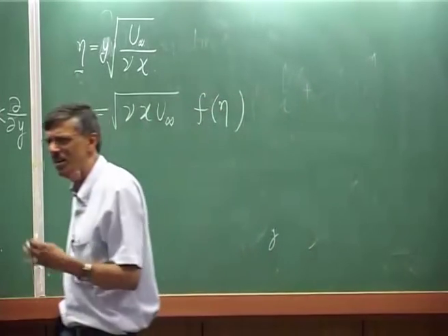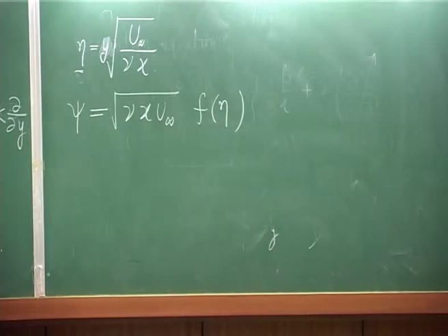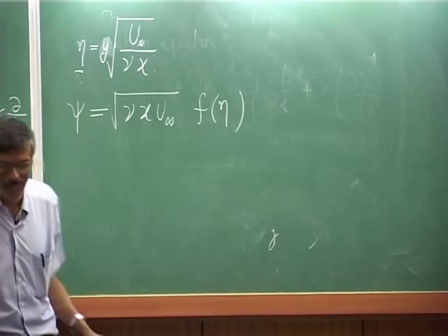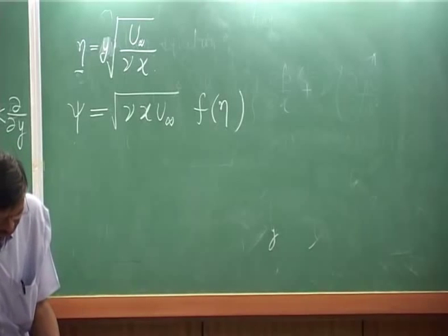So, f is some kind of a non-dimensional function, okay, and the scaling is done with respect to this. Why do we need psi? Well, very simple. I told you, never violate mass conservation, right. So, for this problem, if I introduce the stream function, I am guaranteeing mass conservation. So, this is the ironclad guarantee that you would not fall into the trap of violating mass conservation by the introduction of psi.